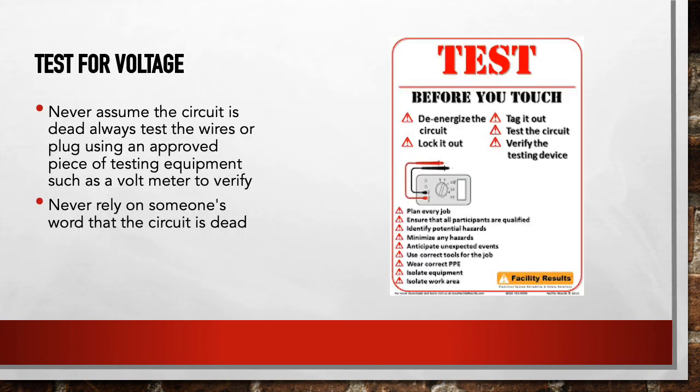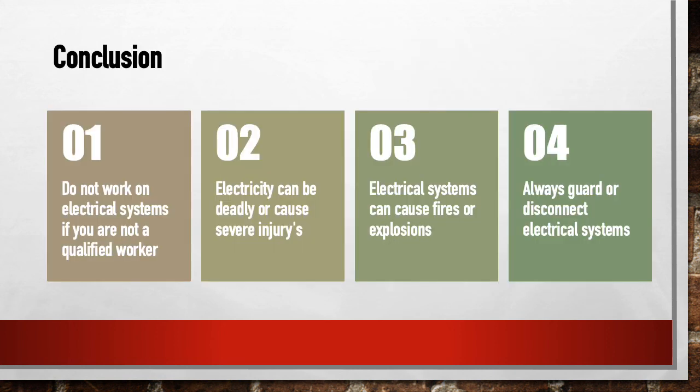So lastly, before you work on equipment, or even if you're authorized, you want to test it. And I'm a 3-try guy. I like to test things out at least 3 times, using essentially a voltage meter, to test the equipment. So you're going to use that, make sure that it's actually terminated, or as they'd say, a closed circuit rather than an open circuit where electricity is flowing. So that wraps up our electrical safety and GFCI section here.